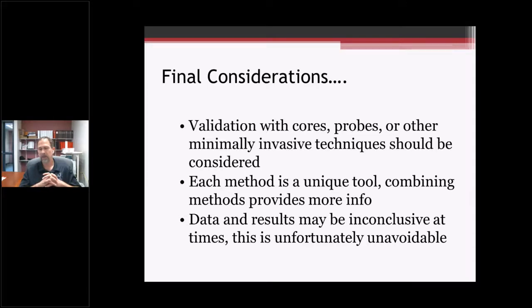It's always nice to have validation of data because these are non-destructive methods, and we don't always know exactly what's going on inside the concrete. You don't have to do it across the whole project, but pick a couple of spots here and there. If you've identified a whole bunch of anomalies, maybe verify with a probe or a core.